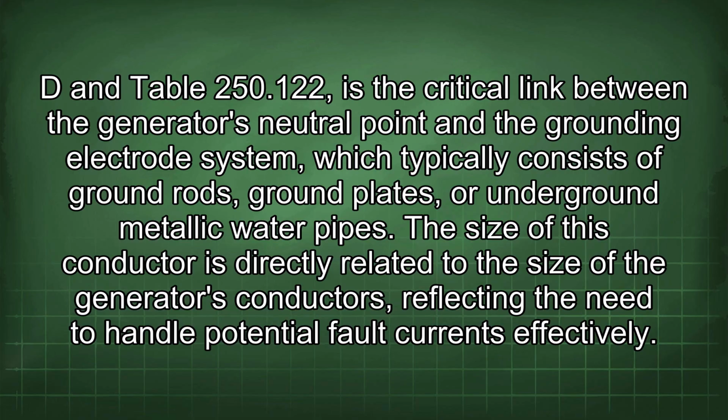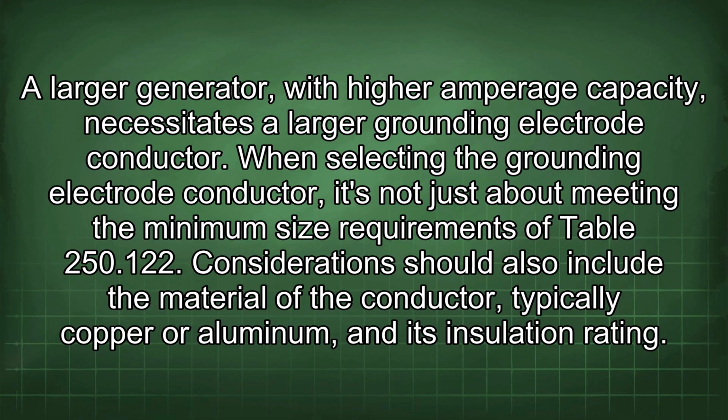The size of this conductor is directly related to the size of the generator's conductors, reflecting the need to handle potential fault currents effectively. A larger generator, with higher amperage capacity, necessitates a larger grounding electrode conductor.